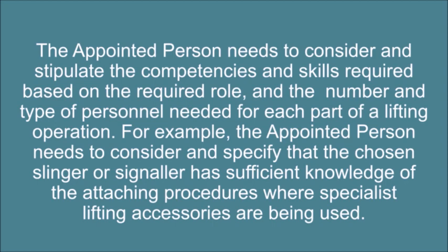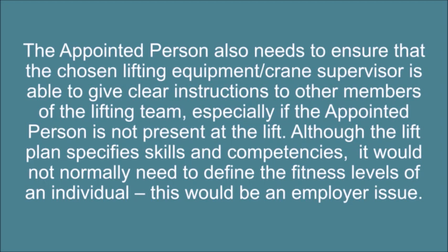For example, the appointed person needs to consider and specify that the chosen slinger or signaler has sufficient knowledge of the attaching procedures where specialist lifting accessories are being used. The appointed person also needs to ensure that the chosen lifting equipment, crane supervisor is able to give clear instructions to other members of the lifting team, especially if the appointed person is not present at the lift. Although the lift plan specifies skills and competencies, it would not normally need to define the fitness levels of an individual. This would be an employer issue.